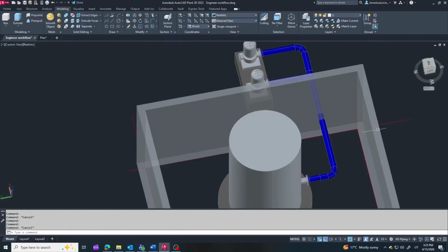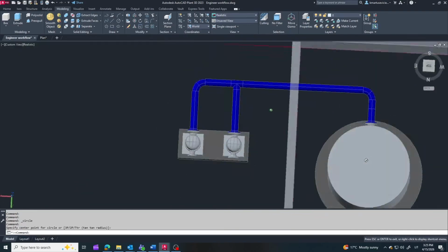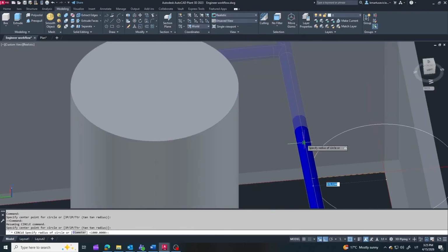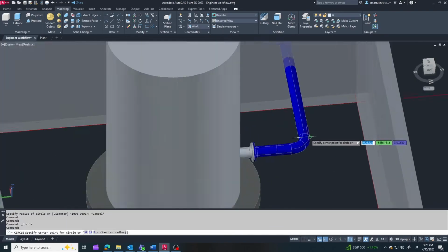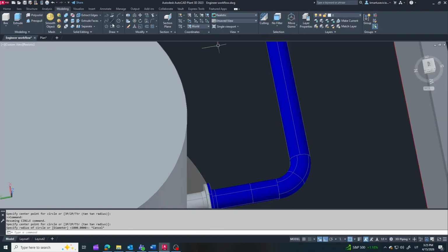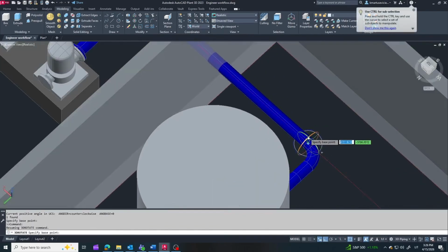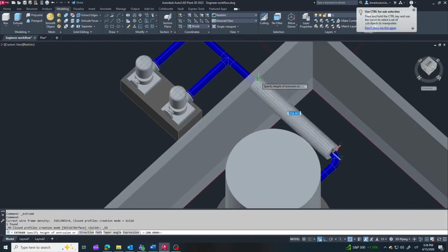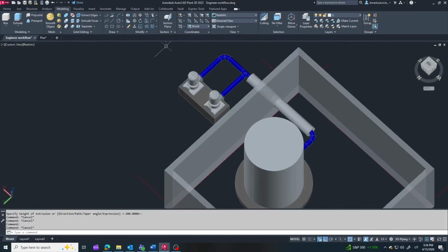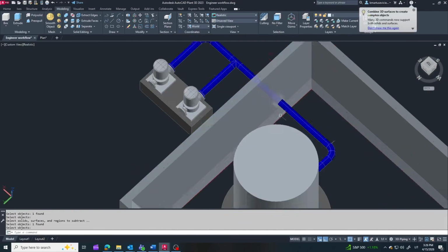In this video, I'm not going deep into detailed 3D modeling. The goal is to show how a project is developed, how tasks are created, and what I'm thinking while modeling. And here we can see where the architectural team needs to be involved. We have a pipe crossing the wall, so we need to create an opening. I cut the required space around the pipe, and this becomes another task for the architectural team.